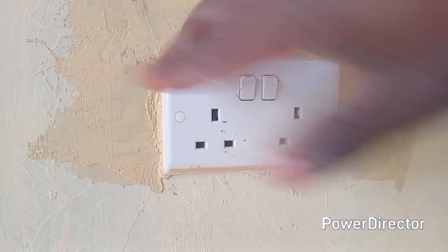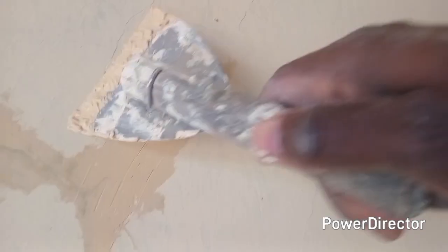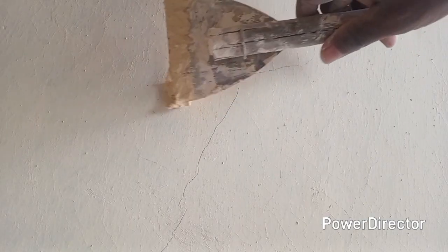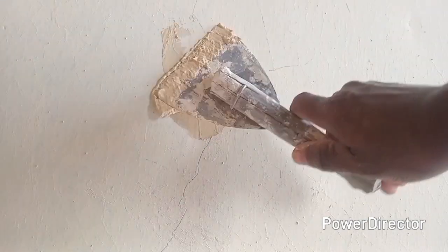And then as for this, I'm going to do sandpapering. We proceed to this and we wipe the excess like that. And then we wipe the excess. As for these indents that I showed you, we simply fill them like that. And then we wipe the excess. This one here, we simply fill it like that. And then we wipe the excess. So I've filled this crack, this indent. What now remains is to sandpaper and then paint over it.